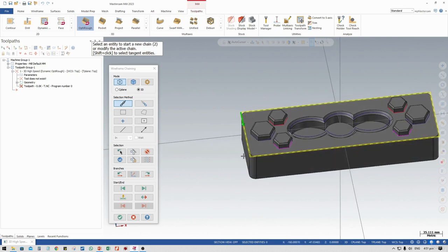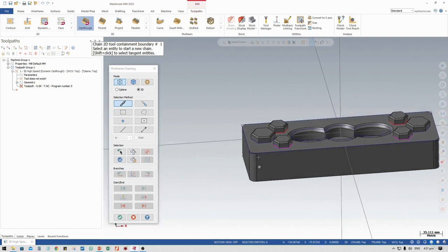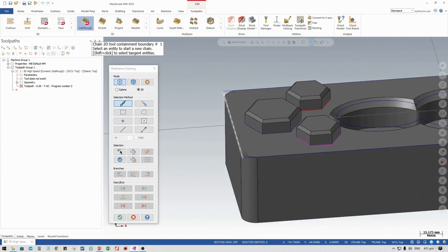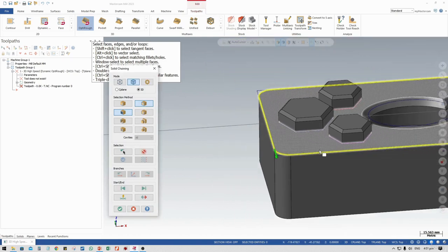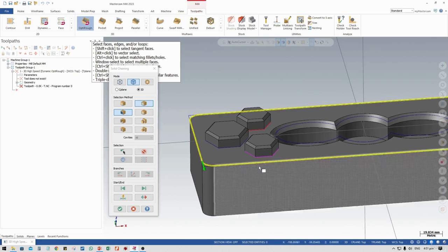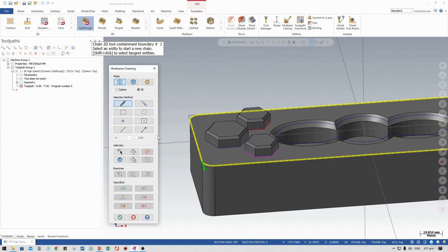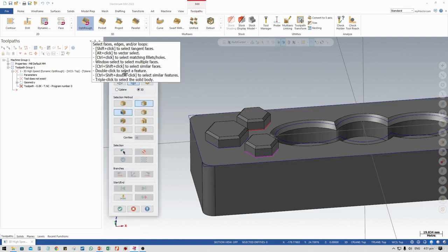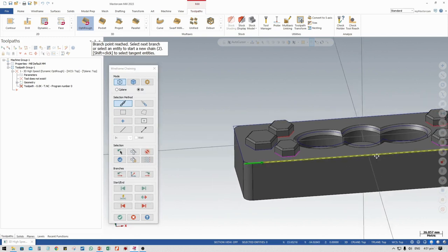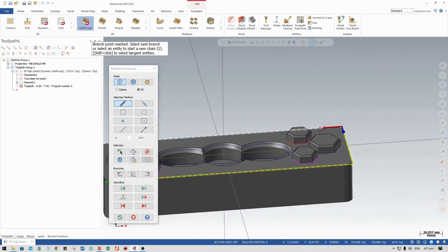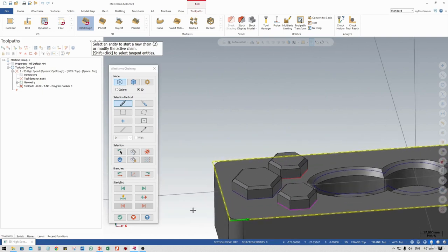Either you have a 2D geometry or 3D geometry, you can select it. For example, let me give you that I'm going to select the 3D, and in 3D we have these corners like this. Okay, so in 3D it selects the 3D edges of the part, solid part, but in the 2D it will select it. Let me go and clear this. Just go to this, and it will select the 2D wireframe geometry. Okay, so you have to select the appropriate method which you are going to use.